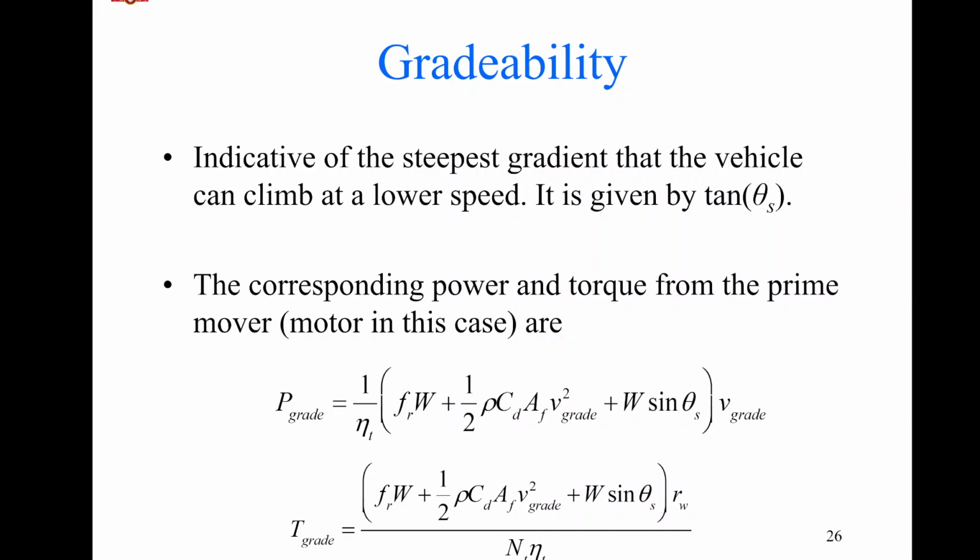So if you want to climb your vehicle on a grade or on a ramp which has angle theta s, its gradability is given by theta s. This is one of the regulatory requirements for a vehicle to get certified for real world use, and the power required in this case would be higher than the power required in the case where the vehicle is expected to move on a flat road.